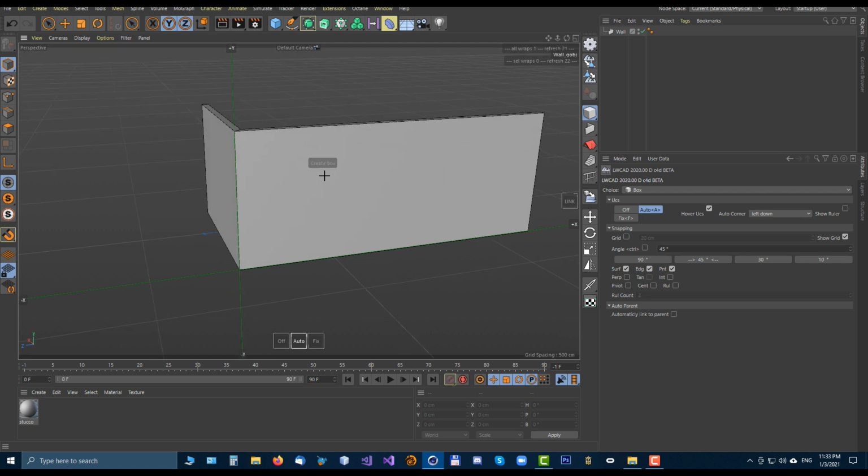You can quickly change mode with the shortcut key A and the shortcut key F. So you can switch to fixed mode. When the UCS is red, it is fixed. If you hit the shortcut key A, you are back in automatic mode.